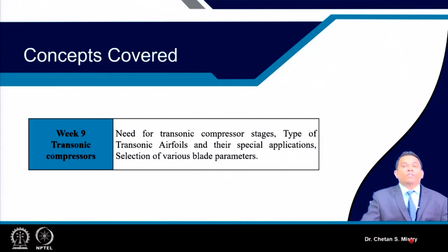Now when we have our flow at the entry to be supersonic, or slightly on the high subsonic side, then we will have initial flow supersonic, followed by a passage shock, which we can treat as a normal shock, giving subsonic flow downstream. The change of flow properties from supersonic to subsonic because of the presence of the normal shock gives us very high pressure rise, and that is what we take as a benefit, and that is what people have explored after the 60s.